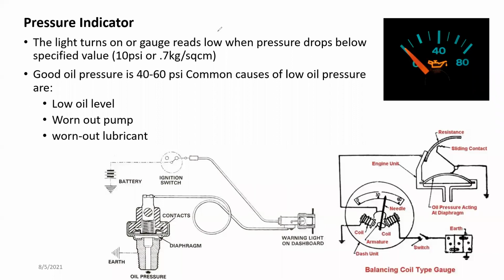This is one of the most important parts of a vehicle. Most people do not care about this as long as there is no problem. It is either a gauge or a light, right? If it is a gauge like this, and it goes below this middle indicator, that means you don't have enough lubricant pressure.